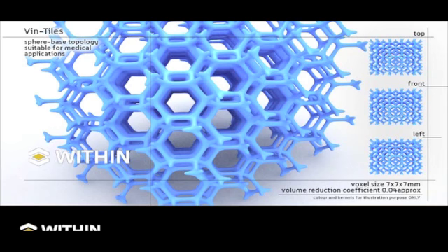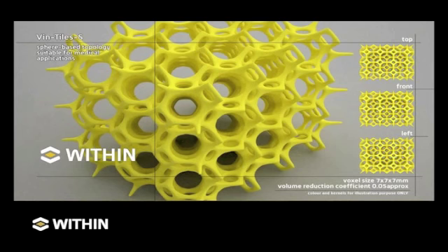Another use for these lattice structures, which you'll see in the case studies, is for what is known as osseointegration. This is the combination and infusion of bone cells into such structures. This is used for orthopedic implants. So when you have an orthopedic implant and you actually implant it into the bone, it's important, and I'll explain this further during the presentation, that the bone cells actually grip on and latch onto the surface as tightly as possible. And what we can do here is create structures such as this that actually mimic the trabecular structure of bone and actually have the right pore size and distribution so that bone cells actually fuse into these 3D printed products.